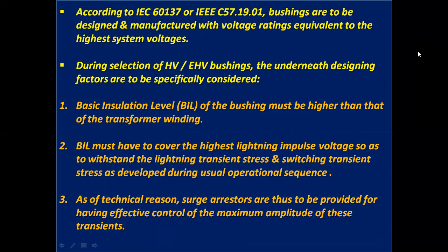Number 1, the basic insulation level, BIL, of the bushing must be higher than that of the transformer winding.